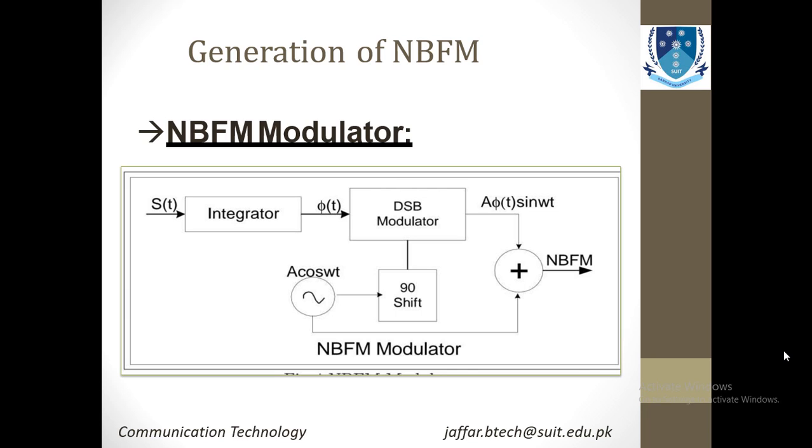Now let's talk about the generation of NBFM and WBFM. NBFM is basically used in small circuits. You just need an integrator and a DSB modulator, just like that of AM, and you have to provide a carrier signal with a phase shift of 90 degrees, and you get your signal.